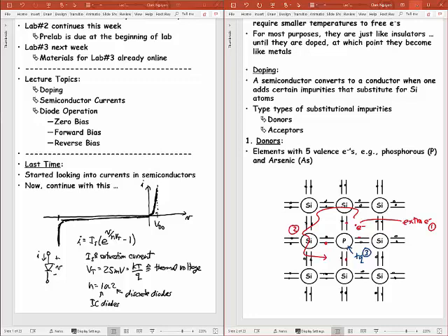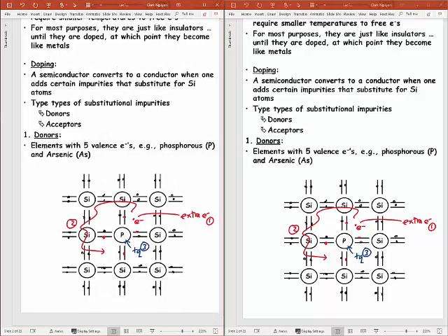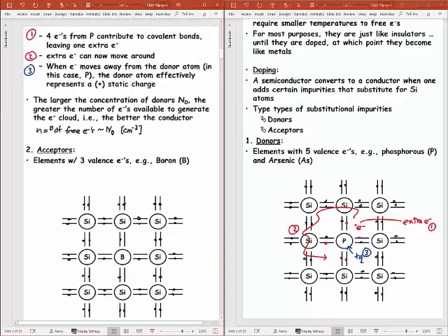In a semiconductor, though, you don't have that naturally, but you can get that by just replacing silicon with a phosphorus. So you notice we've replaced silicon with phosphorus. There's that electron there. It's free to move around. And if I put an electric field around this, that electron will follow the direction of that electric field. Okay? It'll go the opposite direction of the electric field. Okay, so we covered that last time. And so this kind of summarizes a lot of this here.